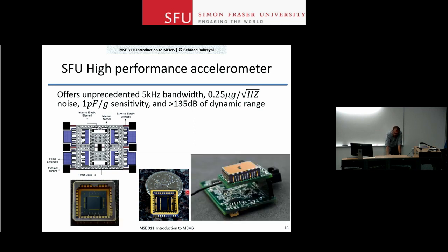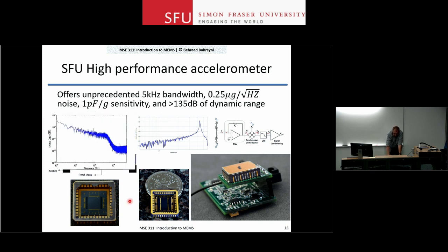With electronics, it looks like this, and the performance of this device is basically outstanding. It's been a few years since we made and published these results. There hasn't been any device that is even close to this device. We have less than half a micro G of noise here and a bandwidth of 5 kilohertz. There is nothing out there that can meet these 2 specs put together.